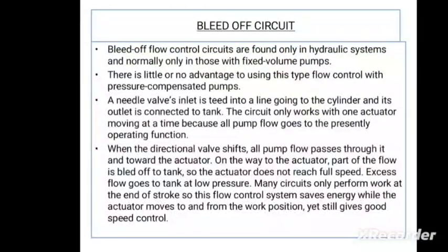This is an important point you might need to know, all of you: the bleed off circuit plays a major role only in hydraulic systems. It is not possible to apply it in pneumatic systems, so only hydraulic systems are possible. And there is little or no advantage to using this type of flow control with pressure compensated pumps.